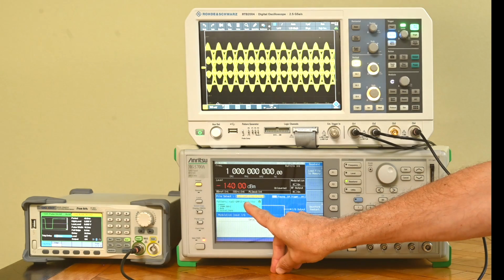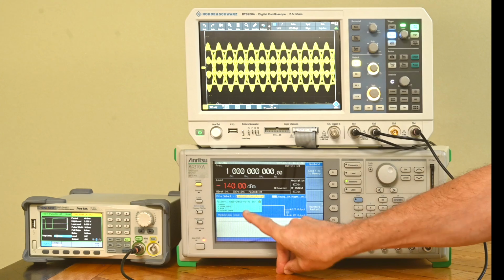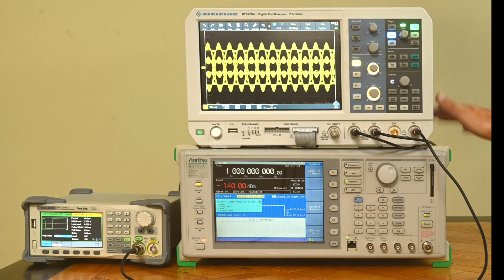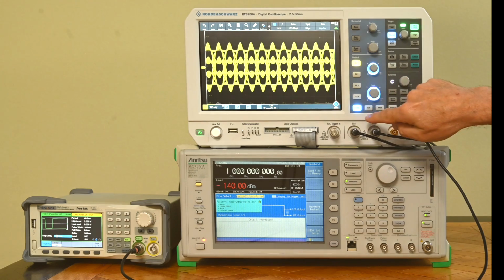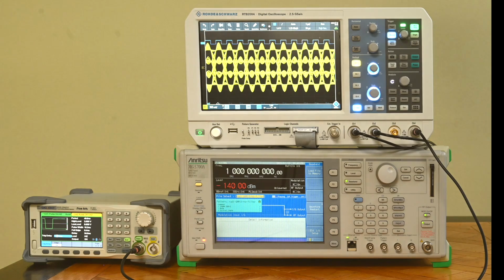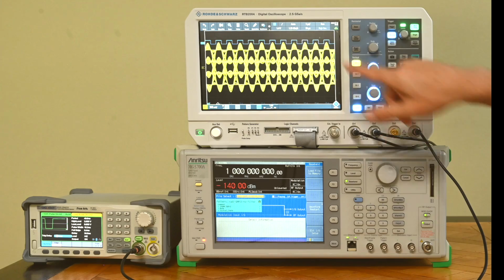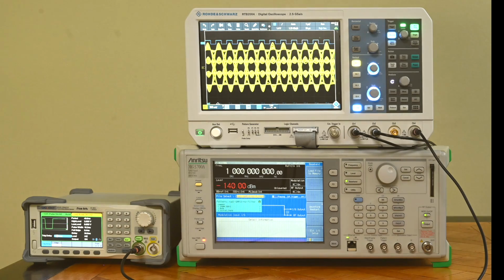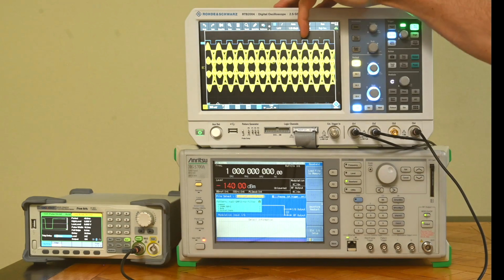In the way that I created the signal here, it automatically comes with a symbol clock, which comes out of the back of the device here on the AUX3 connector. So let me look at that. I brought that signal here to one of the logic channels of the scope. And somehow I want to use this symbol clock here to determine the moment, but I cannot use this as a blanking signal. This is way too wide. I need a very short blanking pulse basically to do this process.